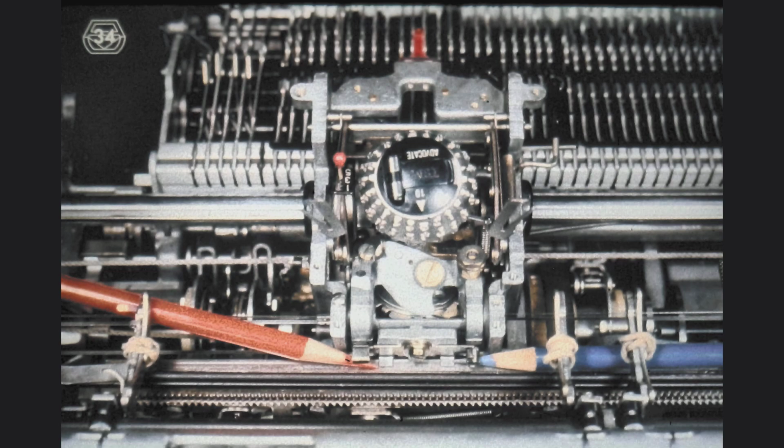This shows a level 3 carrier support bracket. On these later model machines, the carrier shoe no longer exists. Instead, we simply have this bracket fastened to the rear of the carrier. This bracket has 1 lug underneath the escapement rack and 2 lugs above the escapement rack. The spring mounted on the bracket will always keep the rear of the carrier lifted so that the bottom lug of the bracket is always rubbing against the escapement rack, while the spring slides on the top of the rack. Check your machine to verify which kind of carrier support it uses.